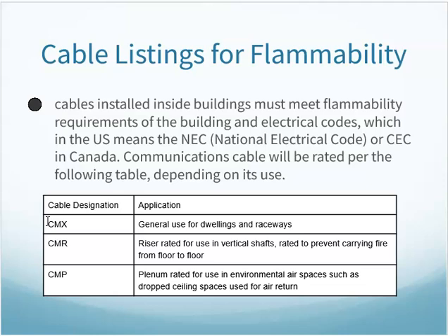Some, if they were to burn, emit a lot of toxic fumes, but other insulations are designed, not that they're fireproof, but if they do catch on fire, they're not emitting that high level of toxic fumes. It might be extremely low or near zero, if you will. So that's when we come into the flammability ratings. Well, the easiest thing to do is look at that last letter. If I look at the last letter, it'll let me know whether it's general, riser, or plenum.